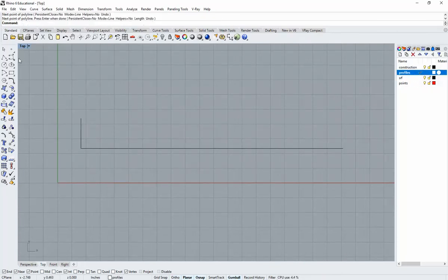Then I'll go over to my profile layer and grab a control point curve, which is up here, and click to that line there. I'm going to hold Shift to set an axis, and I'm going to click once here. I'm going to hold Shift again, click again, and then snap to this construction line. If your snap isn't snapping to the construction line like this, make sure that down below you've got OSnap on, of course, and the Near object snap selected. Very, very useful in this case especially.